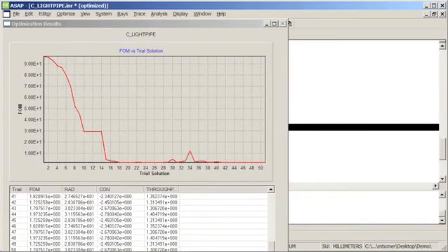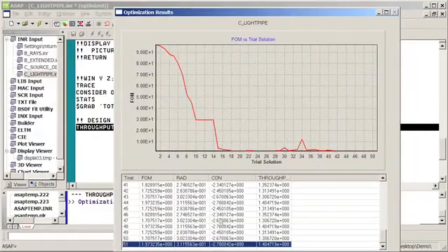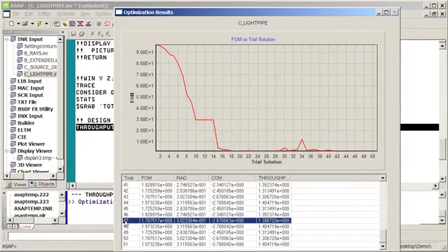And after ASAP has processed the requisite number of trials, the optimization will come to a halt. And as you can see, ASAP was able to find several solutions around a particular maximum coupling efficiency. And again, this is simply because there are a wide range of conic curves, combinations of radius and conic terms that would give us approximately the same solution. Again, we're going to save one of the solutions and just take a look at it. And I will just select, well, for example, this file right here.